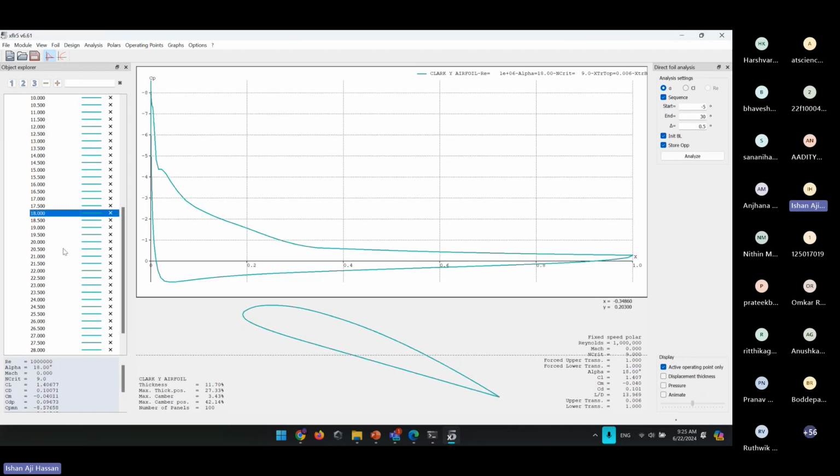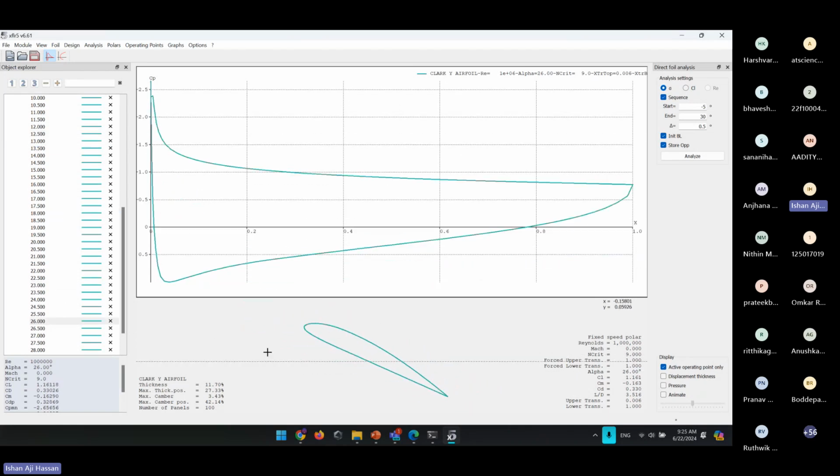If you go to a super high angle, what you can see is that the relative wind is basically this dotted line direction. As you increase the angle of attack, the amount of surface area directly coming in contact with this air is increasing. So your airfoil is starting to look more and more like a flat plate. And the flat plate is basically the highest amount of drag that you can get. It's not very aerodynamic. So this amount of surface area is increasing, and that is why the drag is increasing with your alpha.